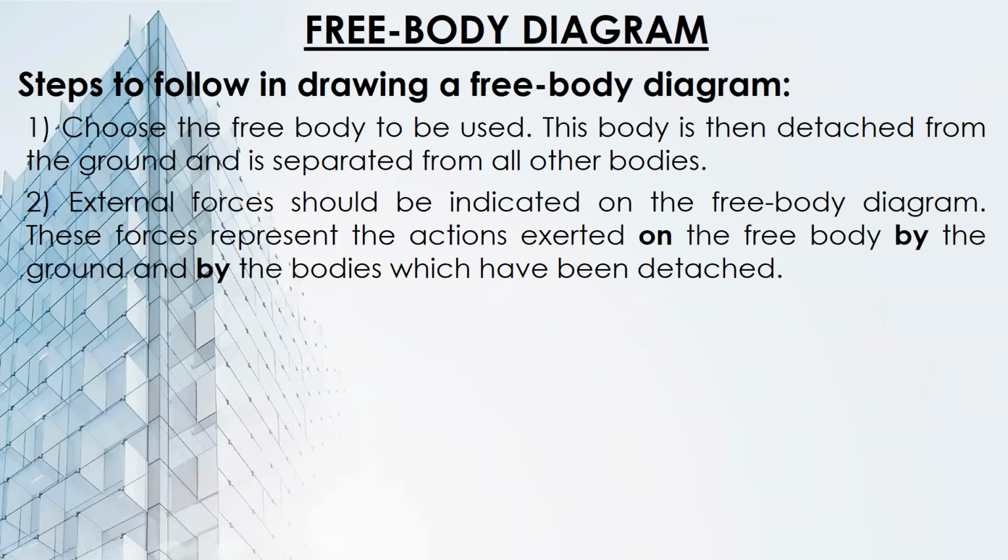Number 2, external forces should be indicated on the free body diagram. We have discussed external forces in the particle topic. So, all external forces should be indicated on the free body diagram, like tension in a cable attached to the body, reaction at the support, those other forces.